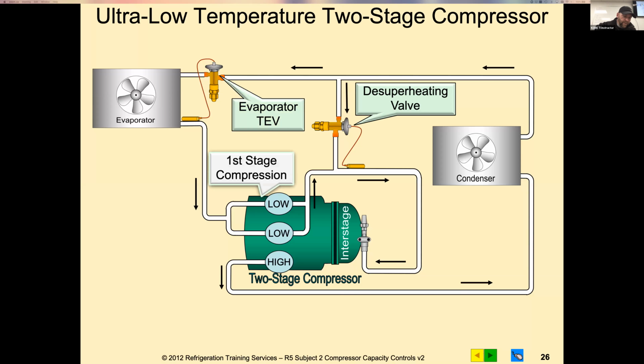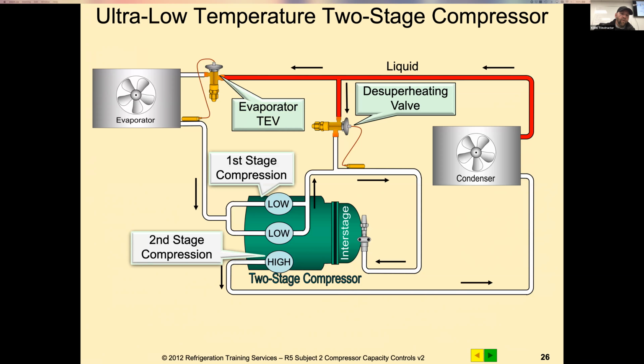So on that first compressor, 2 of the heads is your first stage. It takes that vapor coming right from the evaporator, takes it through 2 of the heads, through a manifold, and discharges right off the top of the heads there. So nothing happens inside of the cooling of the compressor at this point. All of it's happening right there at the heads.